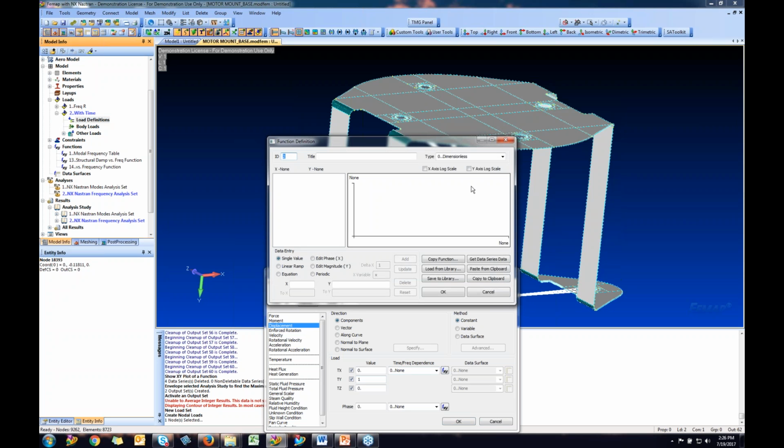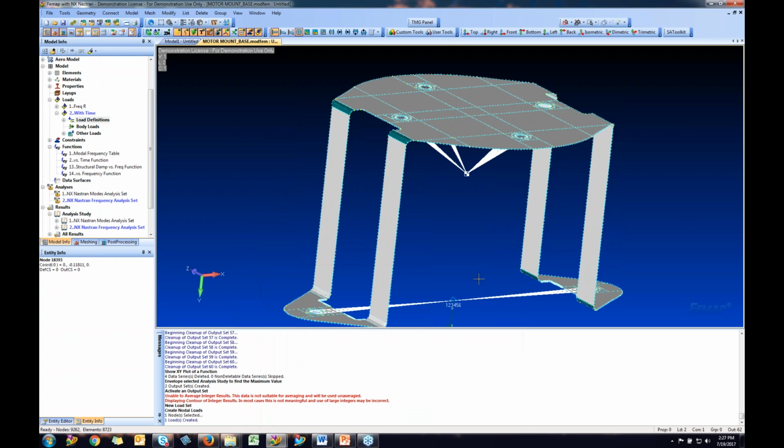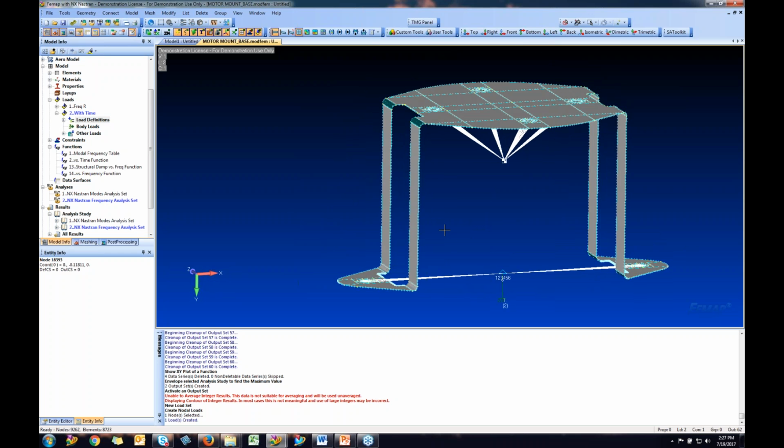So I'm going to define my pulse. I'm going to basically displace this thing for a period of time, this 1 unit. In my case, I need to make sure it's versus time. I'm going to give it a single value. So at time 0, I have 1 of those loads. And then some time down the line, I still have that load. And then some time right after that, my load has let off. And then I'm going to continue that till the end of this chart. So we're just going to impact it with this load from the bottom that's going to push it 1 unit, which is 1 inch in my case, for a short duration of time. So my load is 1 times that. So now I have this input of that load.